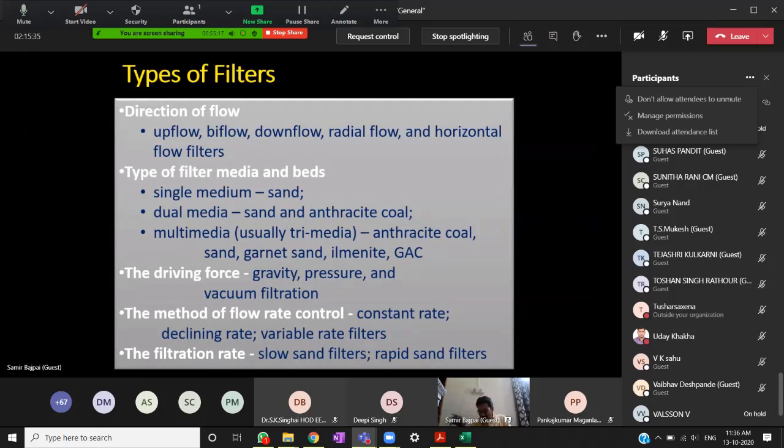The solids will settle based on their size and specific gravity. If single media is there, then larger size particles will have more weight, and they will settle at the bottom quickly, and finer size solids will settle at the top. The problem is that finer size particles will also have fine pores, and then your filter will choke more frequently. To avoid that, you can play with dual media. Anthracite has lesser specific gravity than sand. Then you can have finer size sand and larger size anthracite coal. So after backwash, the coarse size particles settle above and finer size particles settle at the bottom, and your filter run time is increased.